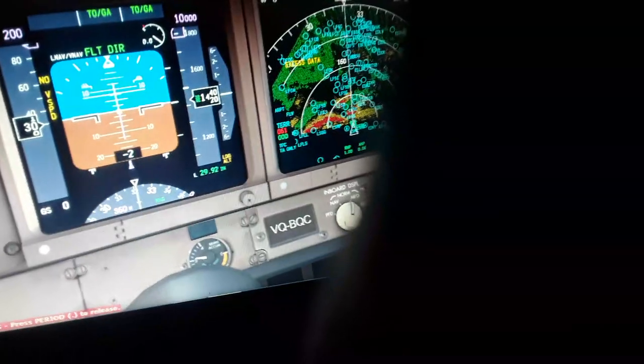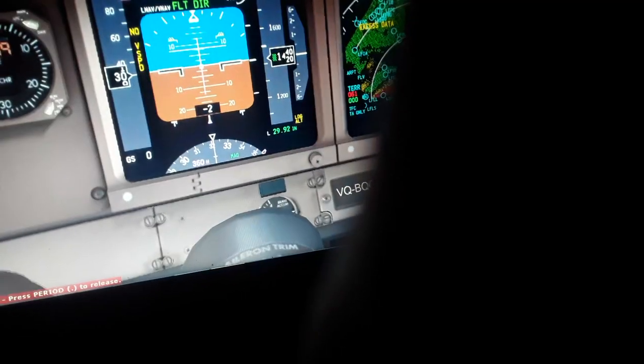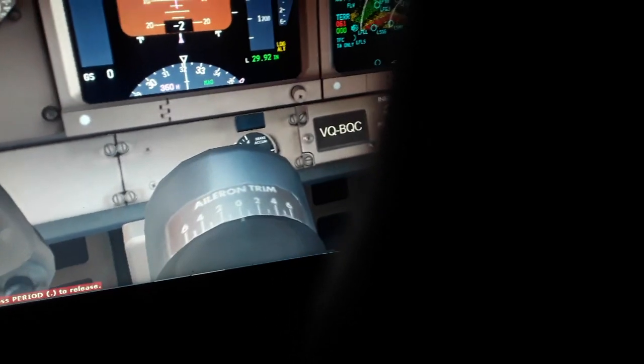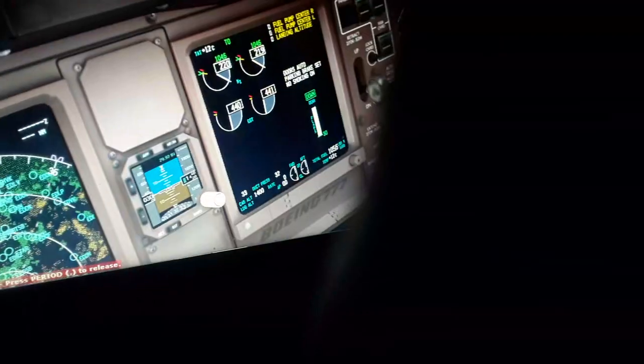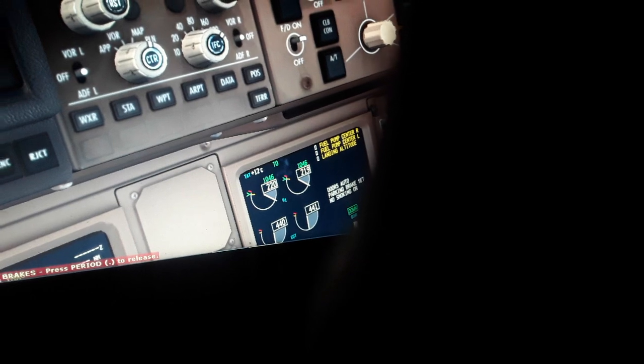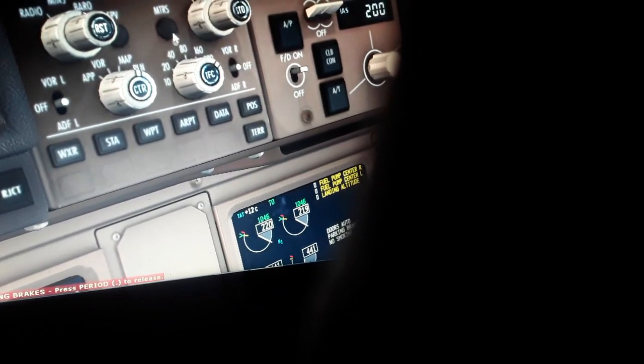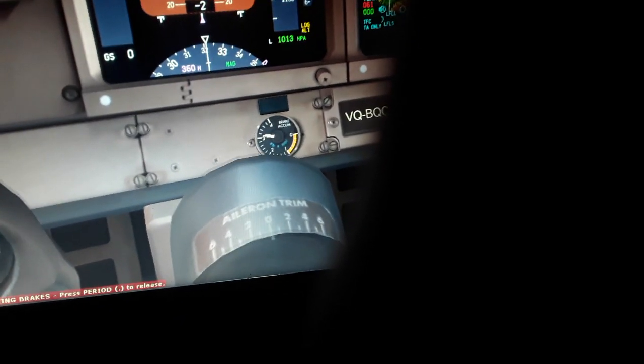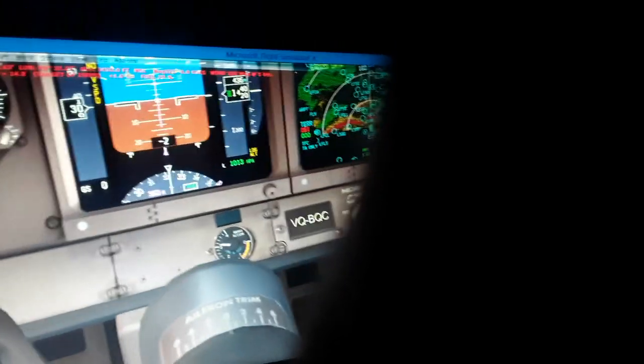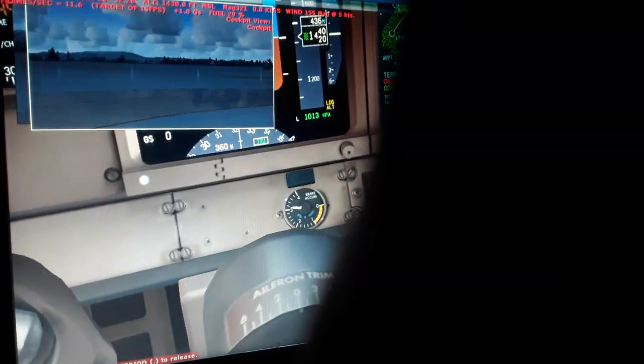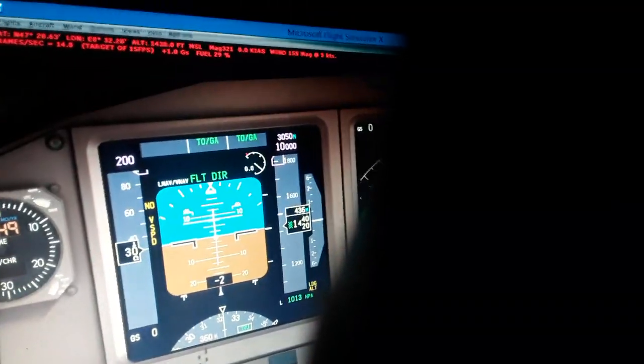You can see here we have also the flight mode annunciator with the autopilot and flight director system panel modes. We can set these in inches of mercury for the barometric pressure, or hectopascals, also to set the meters. For display, we have the north here, magnetic or true, so you can set the true north here, and now we have the true north for navigation.